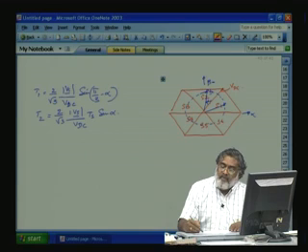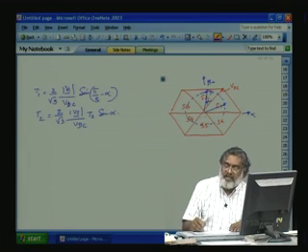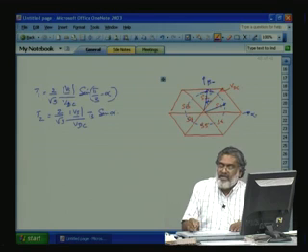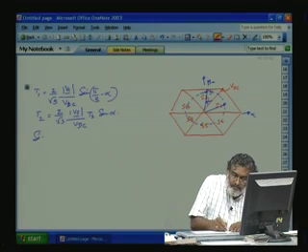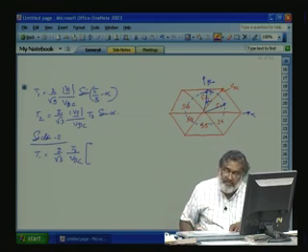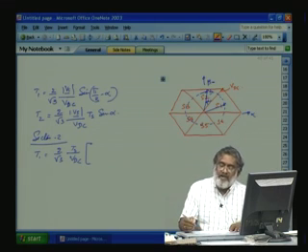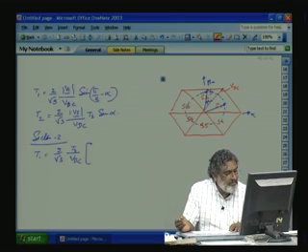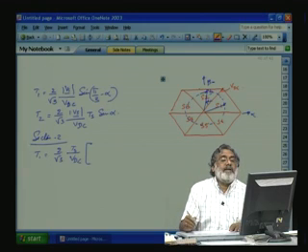And Vs sin alpha will be perpendicular to this one. So, we have to find out the alpha component along the start of the sector and perpendicular to it in sector 2, where alpha is placed along this axis. So, if you see here, sector 2, T1 is equal to 2 by root 3 Ts by Vdc into the component along this direction, that is Vs cos alpha in sector 2.